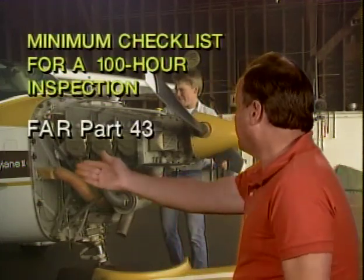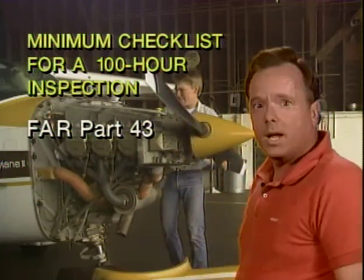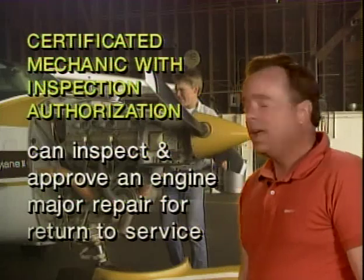All right, where would you find, they're going to say, super mechanic, a minimum checklist for a 100-hour inspection? Well, once again, here you're going to look at Federal Aviation Regulation Part 43. It's the minimum, I'm saying, checklist for a 100-hour inspection. What can a certificated mechanic with an inspection authorization do? That's the question they're going to ask you. Well, the answer is they can inspect and approve an engine for major repair for return to service. So if you want to have an inspection and approval for a major repair, you'd have to have an IA, inspection authorization.